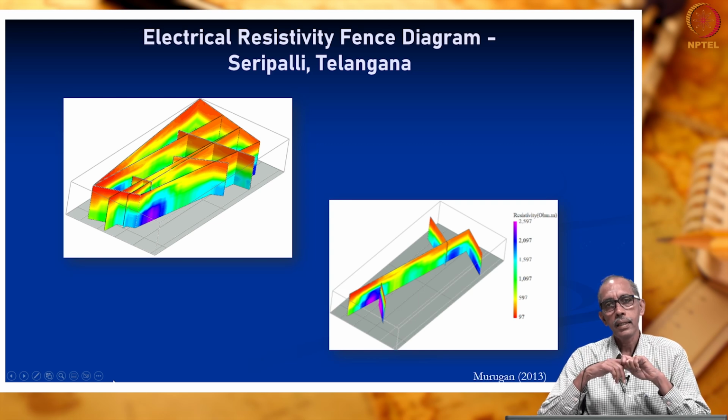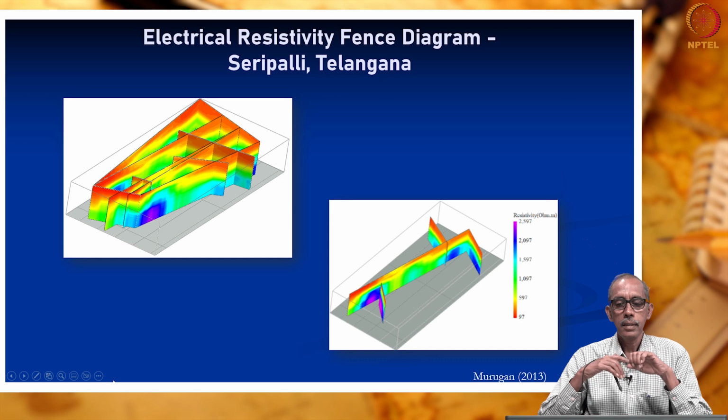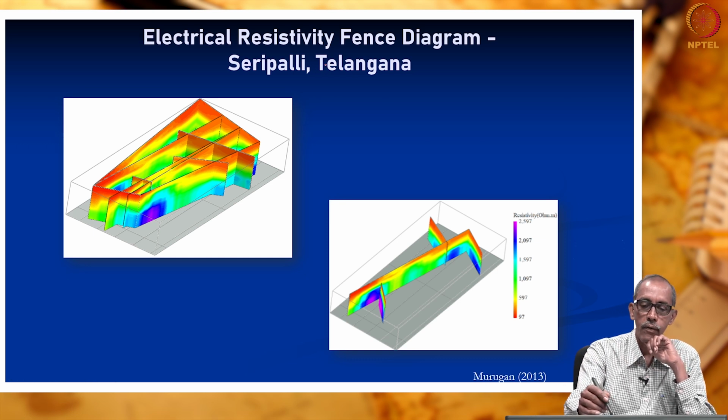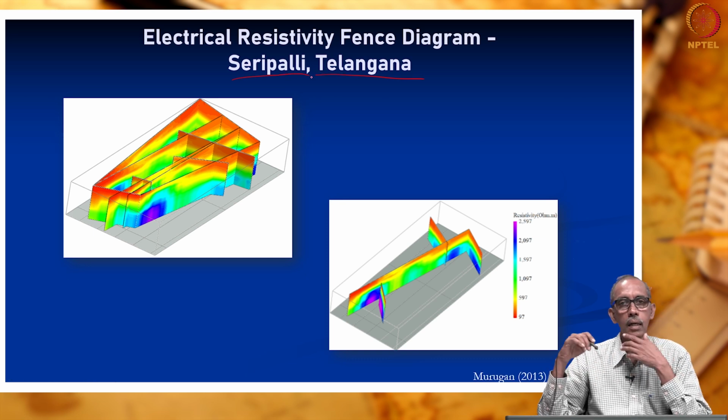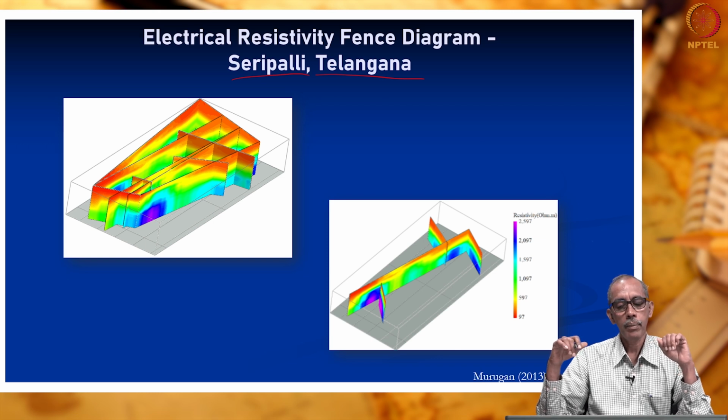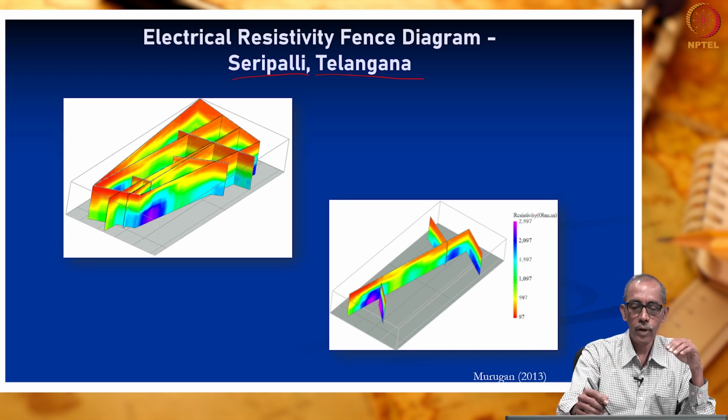Then we did another study to understand the subsurface geology. This study was carried out in the state of Telangana in a region called Sripalli, wherein we did vertical electrical sounding at different locations. Why did we carry out this study? Mainly to understand the subsurface geology. In order to understand the subsurface configuration, we conducted electrical resistivity sounding at different locations, right.